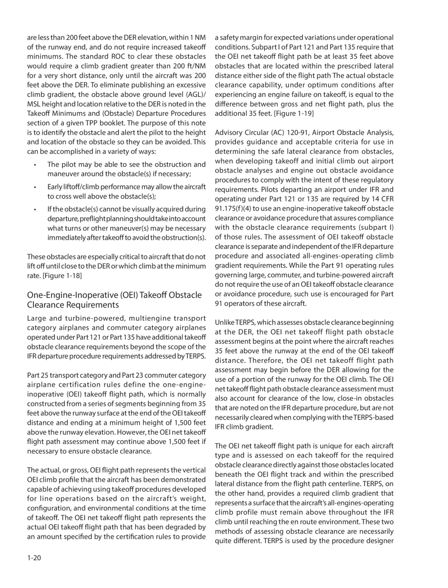Pilots departing an airport under IFR and operating under Part 121 or 135 are required by 14 CFR 91.175(f)(4) to use an engine inoperative takeoff obstacle clearance or avoidance procedure that assures compliance with the obstacle clearance requirements, Subpart I, of those rules. The assessment of OEI takeoff obstacle clearance is separate and independent of the IFR departure procedure and associated all engines operating climb gradient requirements.